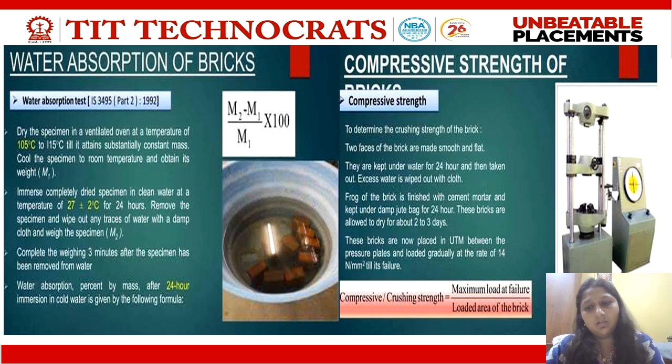I take a few sample bricks from the stock and measure the weight, the initial weight M1. I immerse the brick in water for 24 hours. After 24 hours, I remove the brick, clean its surface, and weigh it again as M2. The water absorbed is equal to (M2 minus M1) divided by M1, into 100.